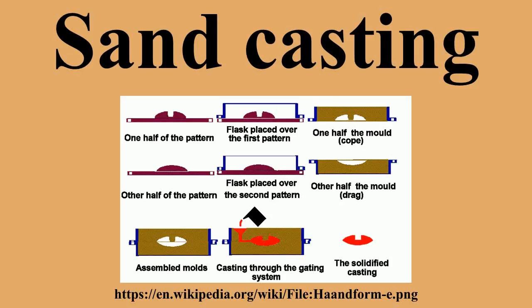After casting, the cores are broken up by rods or shot and removed from the casting. The metal from the sprue and risers is cut from the rough casting. Various heat treatments may be applied to relieve stresses from the initial cooling and to add hardness, in the case of steel or iron, by quenching in water or oil.